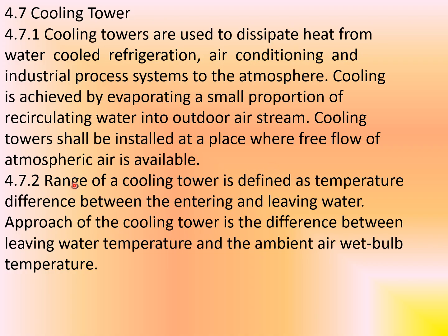The range of cooling tower is defined as the temperature difference between the entering and leaving water. Approach of the cooling tower is the difference between leaving water temperature and ambient air wet bulb temperature. Now, these two definitions are necessary to understand the theory of cooling towers. These two terms are required for selection of a particular type of cooling tower.